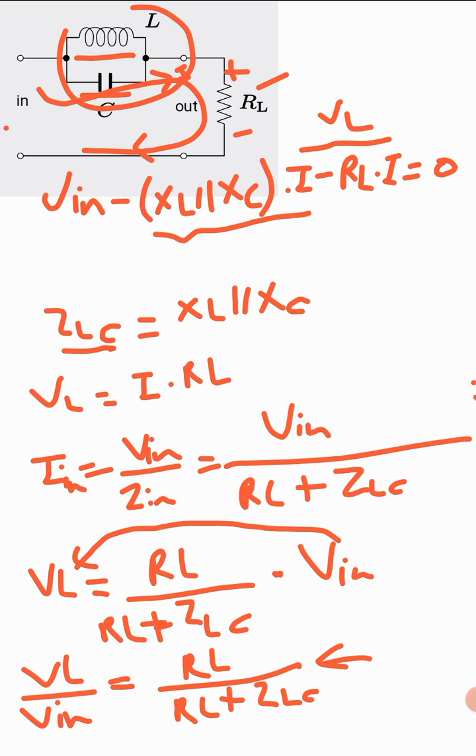So we are able to calculate the effective impedance, voltage gain, output voltage, input current, etc. We are able to apply Kirchhoff's voltage law also to get this very first equation. Kirchhoff's voltage law allows us to calculate the drop across each of the components and sum them all and equate it to 0. That is what the KVL says.